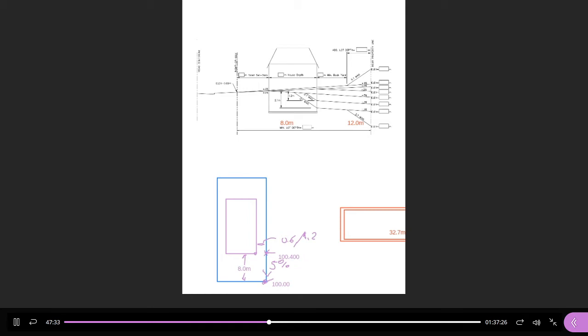Now, when you look at a cross section of a lot, I'm going to look at this section. You see the wall of the house, and then you see the property line. Whatever the elevation is opposite the corner, the elevation at the house is going to be higher by about 0.15 meters, or at least 6 inches, or 15 centimeters.